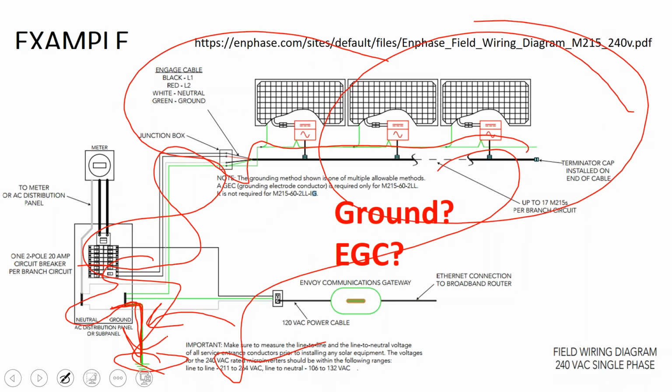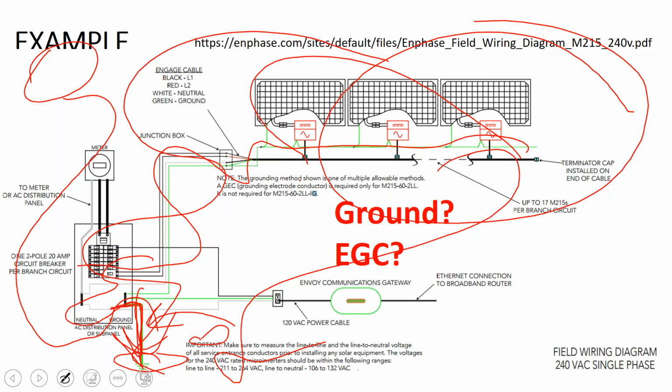And on top of that, you might have a circumstance where you have a DC side and an AC side, and on that DC side, the ground might be connected up in the same spot. They might share it. So you might have a DC grounding electrode conductor that's being carried through the AC equipment ground conductor. And so when you're sizing your grounding system, you have to think, is this the only connection of my DC system to ground? What's that wire size? If you're combining your DC and your AC grounding systems, being that you're at a higher voltage on your DC side, or a different voltage and different amperage on your DC side than on your AC side, it may come that your DC side requires a larger cable.